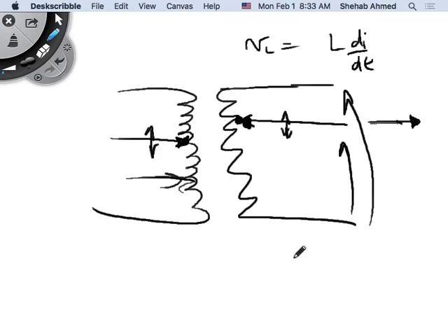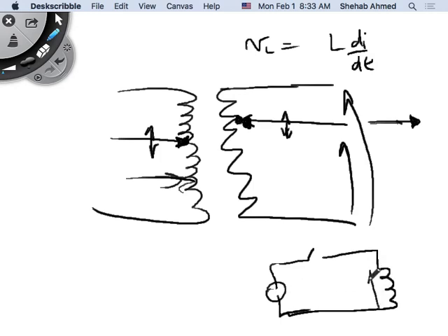If I think of my system as this switch, my load inductor here, and my source, then if my source is a small voltage, for example, this large voltage will be developed across the switch, and I will have arcing happening. If you have arcing happening, then this is submersed in oil, right? This is all submersed in oil. Then what's going to happen? You'll be burning that oil, right? If you burn that oil, then you're adding impurities to the transformer, right? You add impurities to the transformer, then your insulation integrity is no longer there, right? You lose the insulation integrity here.